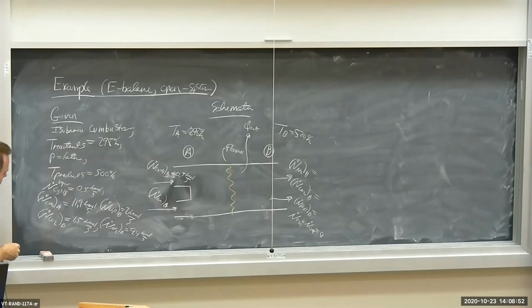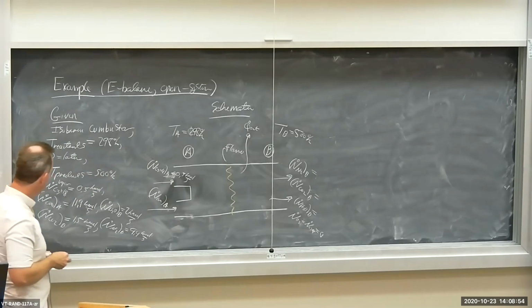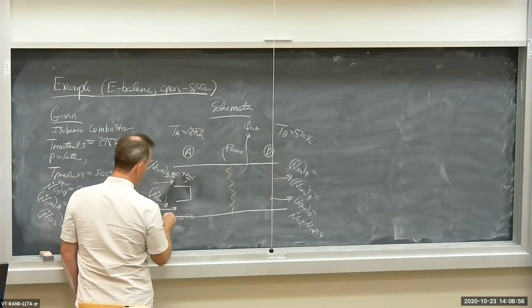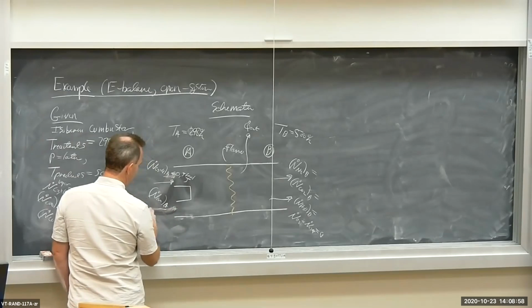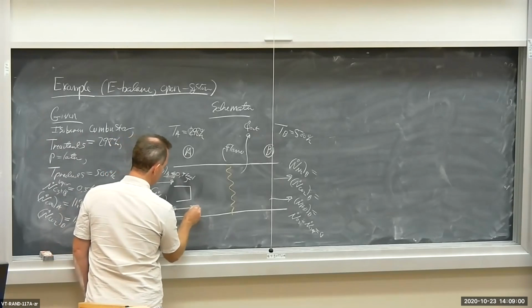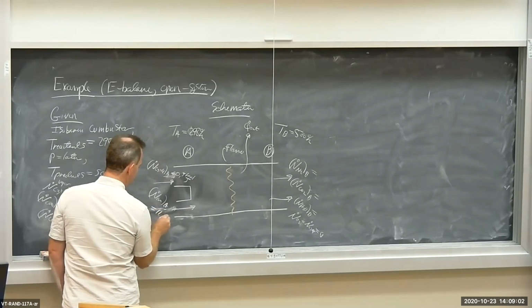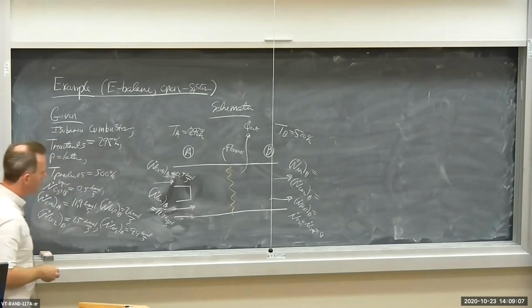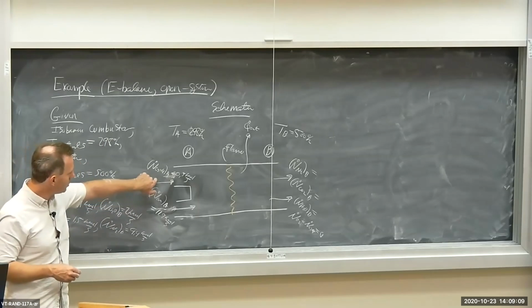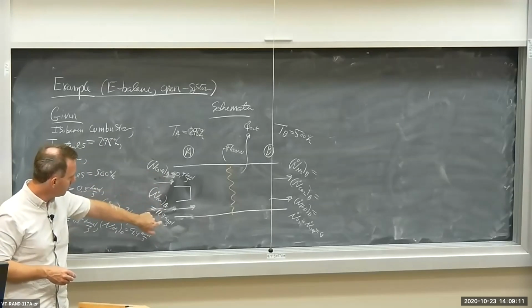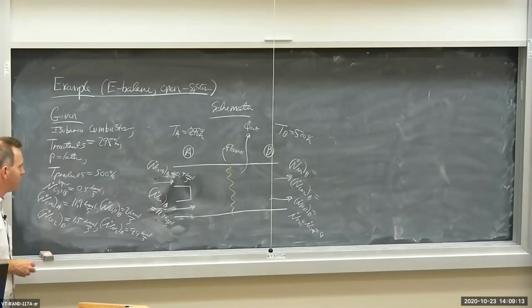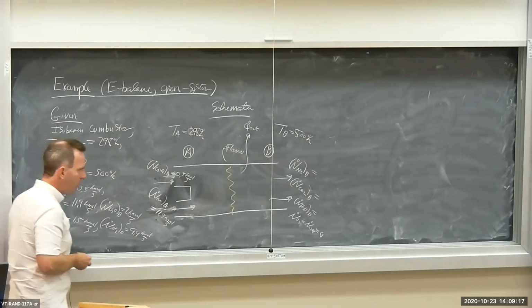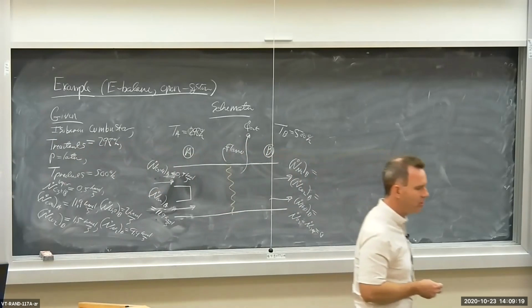So N dot C3H8 is 0.5 kilomoles per second flowing in. And I'm mixing it with 11.9 kilomoles per second of air. So N dot for the air is 11.9 kilomoles per second. This is the reactant side at 298 degrees Kelvin, propane and air. Remember, air contains 21% O2 and 79% nitrogen.